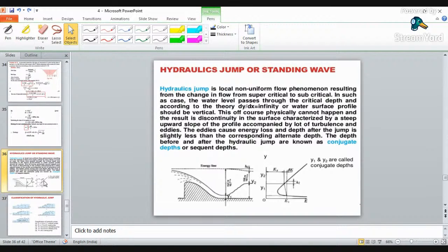Just observe this figure. Here, at the left hand side, at the downstream side, water is coming. Suddenly there is an obstruction. Because of that obstruction, there will be a sudden change in the velocity, the pressure and the cross sectional area of the channel. Because of that, there is a sudden rise in the water height. Is it? So that is nothing but your jump. So what is a hydraulic jump? It is a phenomenon that is frequently observed in open channels such as rivers, canals, spillways or weirs, which dissipates an excess amount of energy.